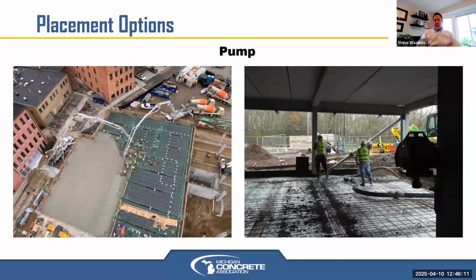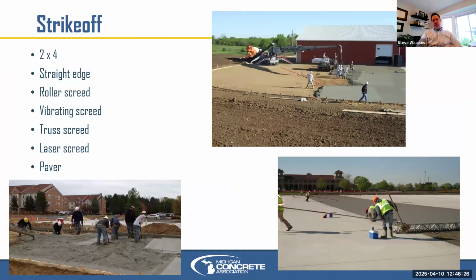You may need a pump. Obviously, a lot of structural concrete uses pumps for floors and parking structures and things like that, like are pictured here, but they are sometimes used for pavements and flat work as well. Line pumps or boom pumps, depending. And then strike off equipment. There are a ton of options for strike off, but let's pause for a question.